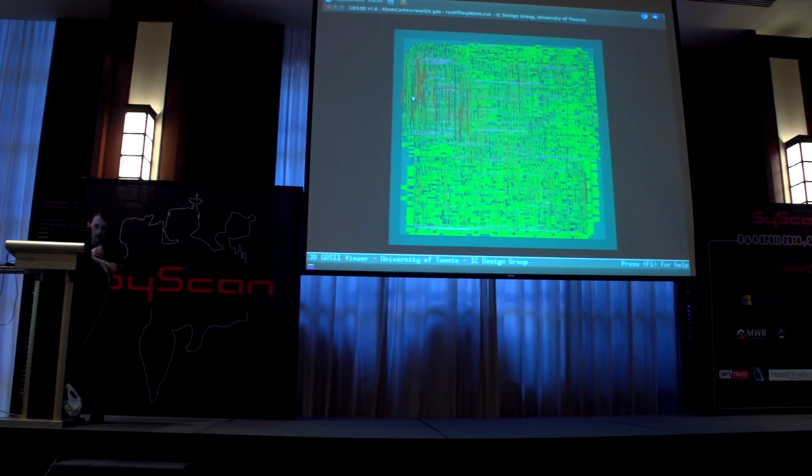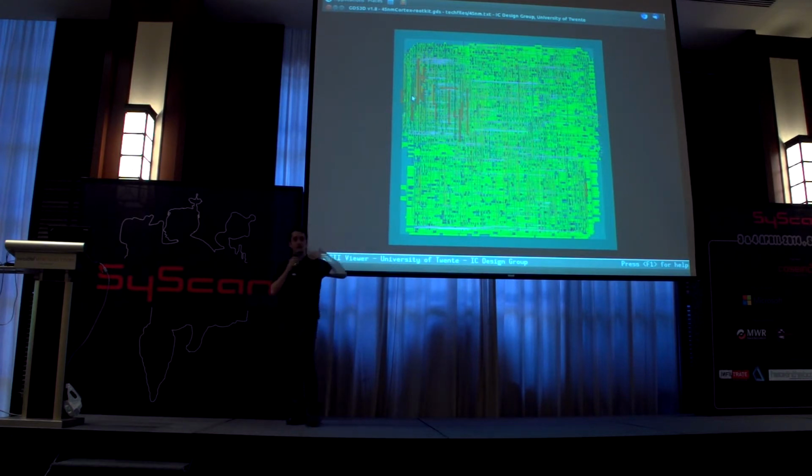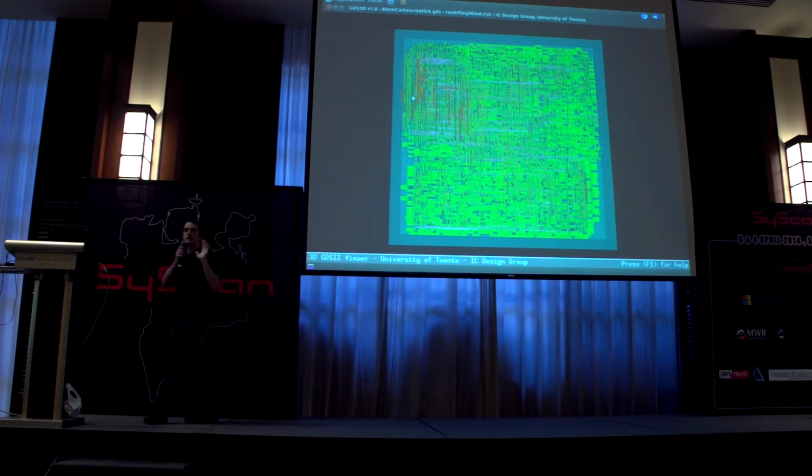Okay, so this is a 45 nanometers chip. It has 10 layers because when you decrease the size of the process, you can also increase the amount of layers. So you have a lot of layers. You can see that the backdoor is one piece of the CPU die that is different. It's that one, because of the code style that you use, it gets synthesized in a different way. So only by looking at it, you can see that there is some code that is different than the other. Let's see more closely.